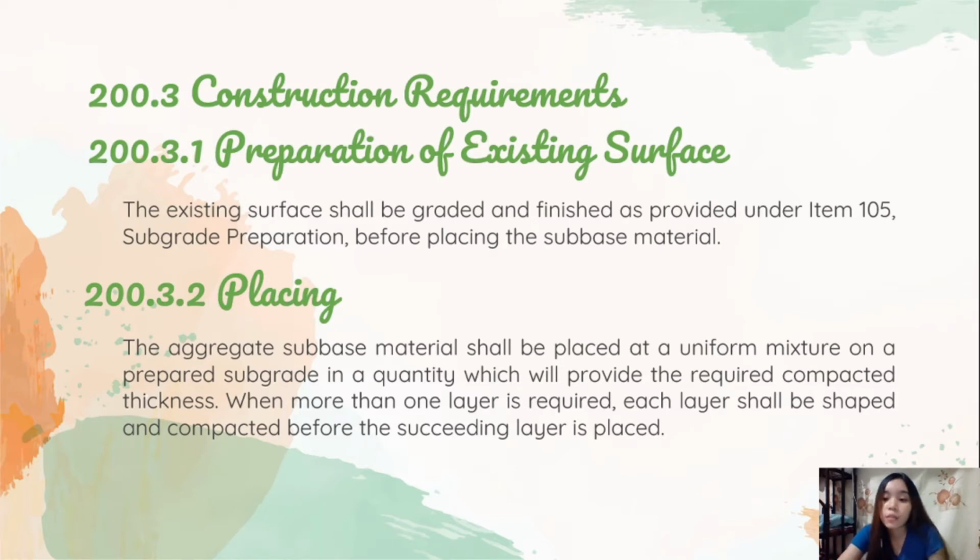The placing of material shall begin at the point designated by the engineer, and placing shall be from vehicles specially equipped to distribute the material in a continuous uniform layer. The layer shall be of such size that when spread and compacted, the finished layer will be in reasonably close conformity to the nominal thickness shown on the plans.